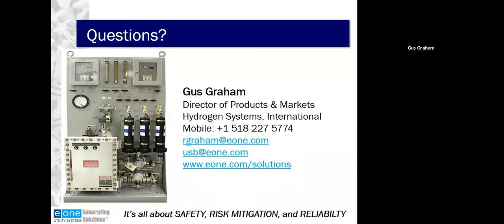So bottled gases have a dew point of minus 70 degrees centigrade. The only thing I can think of that would affect the gas would be a contaminant, and you're getting 4 or 5 nines worth of gas. So I don't believe that there's a shelf life concern, whether it's from bottled gas or from a local H2 generator to a bulk storage tank. But again, this is best passed along to whomever your supplier of hydrogen is, just to confirm that.